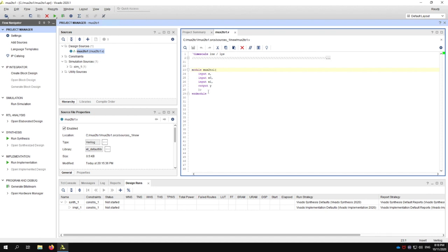And the third thing is that when you're working on group projects or team projects, it's not necessarily future you who's going to look at your code, but maybe somebody else that you're collaborating with, a colleague. Maybe you'll have left the company by then, or you'll be on another team. But they are going to need to modify your code, maybe because they're debugging or troubleshooting, or trying to add functionality. And the comments will be much more readable for them than Verilog code. So for all those reasons, commenting your code liberally is extremely important.